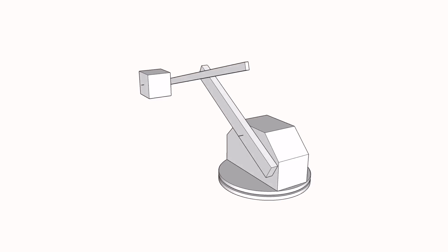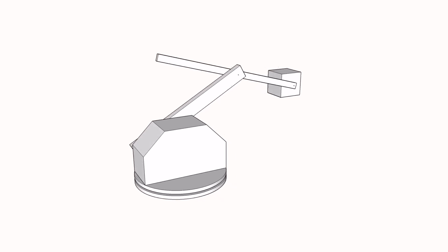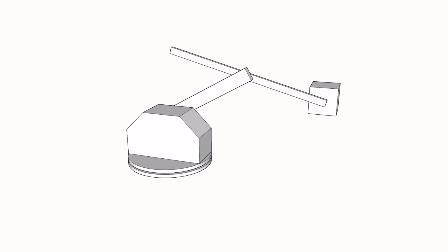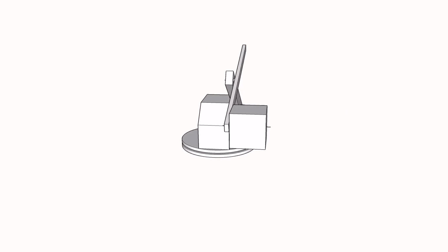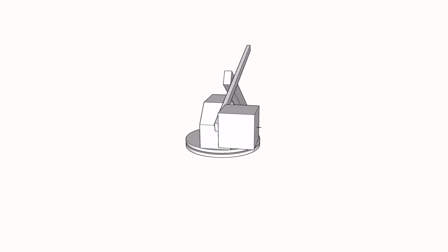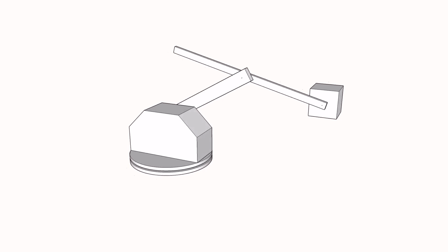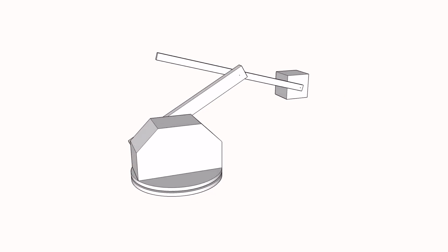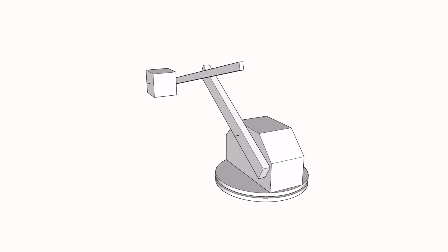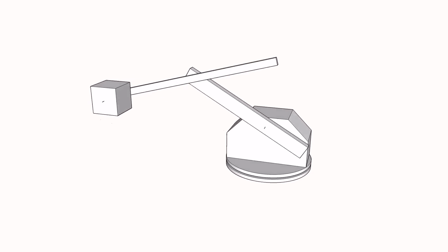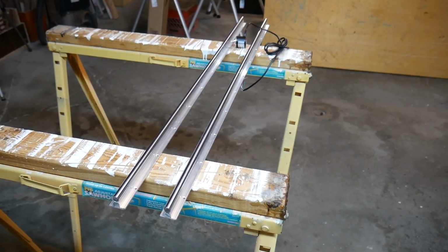And I've also started thinking about what the final one's going to look like. I was originally quite enthusiastic about having 360-degree rotation on the arms, because I felt like that would give me quite an advantage, or at least it would look cool. And then I realized that it would look cool, but that's it, and it wouldn't be much of an advantage. As long as that base can rotate, you can do almost everything that I was hoping to do with the continuous rotation. And if we take out the continuous rotation on those arms, it'll make the mechanism a lot simpler. They won't have to be cantilevered out like they are in this animation, which will make the mechanics of it simpler to make. So I think we're going to skip that for now, and make it a bit simpler.